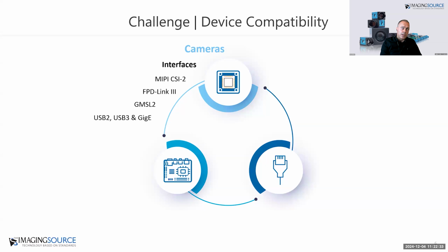Sometimes, and I heard it today too, when speaking about embedded, some people think about MIPI CSI2 only, but it's not only that. Of course, we have technologies based on MIPI CSI2, like GMSL2 or FPD-Link, that use a deserializer technology to extend the cable length and are definitely more suitable in harsh environments. But embedded vision could also be USB and GigE, exactly the same way. So it depends on the application, on your requirements, and on what eventually does the job for you.